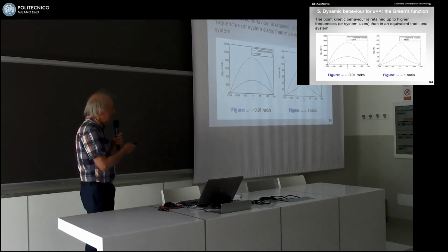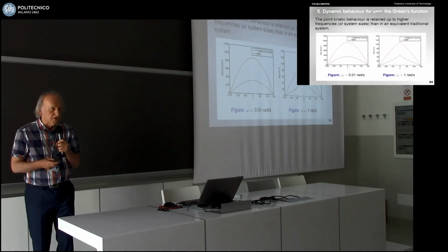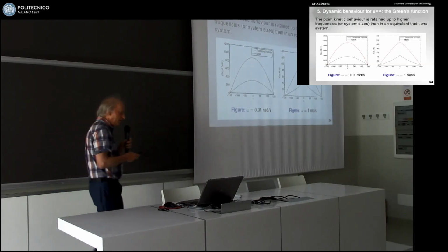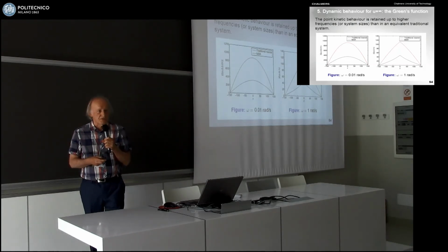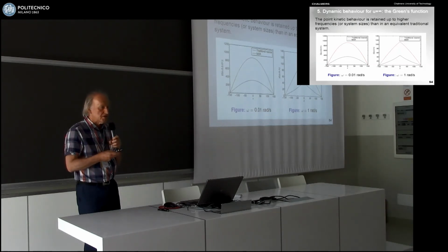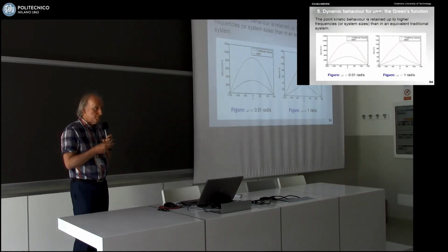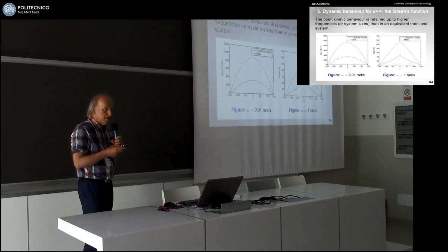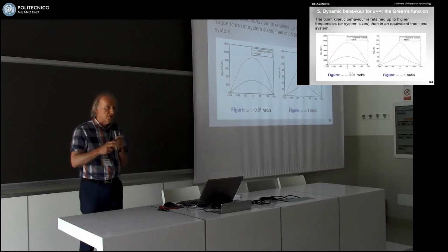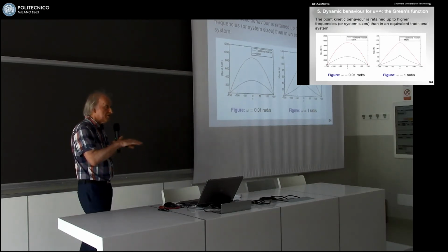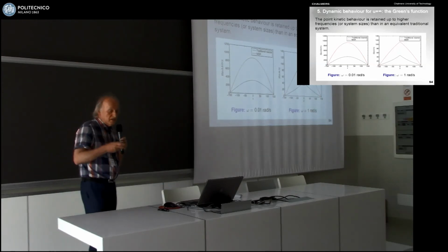The other thing is that the noise amplitude will be much bigger, and if there are people here from Spain, they know that, and even Germany, there is a type of German reactors, this older convoy reactors, in which the natural fluctuations have become so strong that those reactors are not allowed to be run on 100%. And the explanation is still not clear why this happened. It's just that the fluctuation is so big that the safety system gives alarm signals all the time. Now, if it comes to that extent, it's not good.